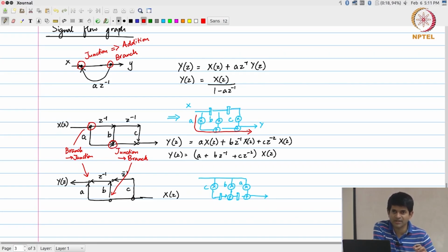Yeah, there are a lot of optimizations you can do. But at the end of the day, there are a whole lot of adders that are going to end up in your critical path. Whereas over here, the critical path is essentially going to be always 1 multiply and 1 add. Fundamentally, it has been changed in such a way that after every adder there is a register. So the output of the addition basically goes into a register, and in that way effectively what we are saying is that no matter how many taps this filter has, the critical path is always going to be restricted to 1 multiply and 1 add.